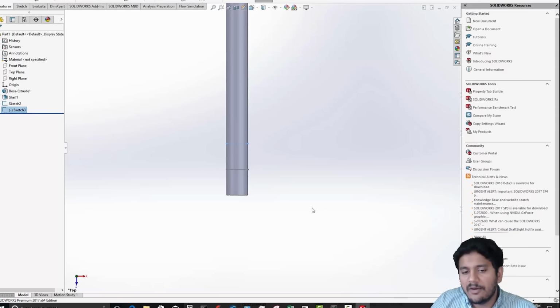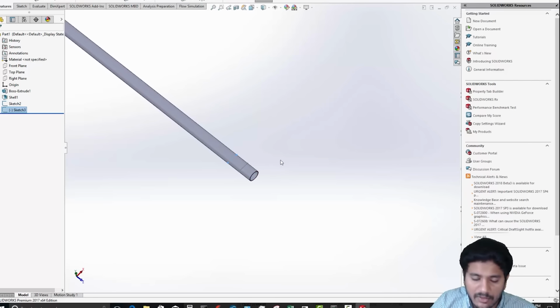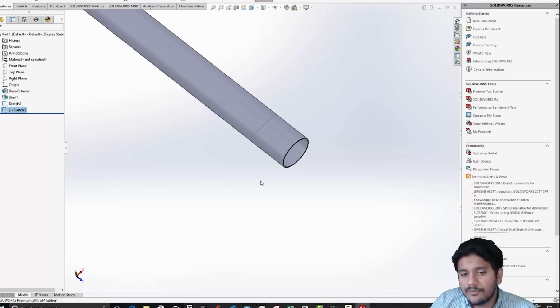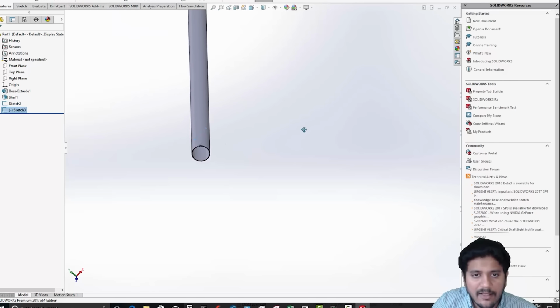Okay, so our objective is to plot the velocity, pressure and shear stress across these lines to see how they change. And you can actually learn a lot about the simulation by creating these type of line probes. And in a later video, I'll show you a different problem, which is called the backward step flow problem, where I'll also show you experimental data that has been measured across these lines. We'll take a look at the relevant paper and the results that were obtained. All right, so now that I have my line probes, I'm all set.